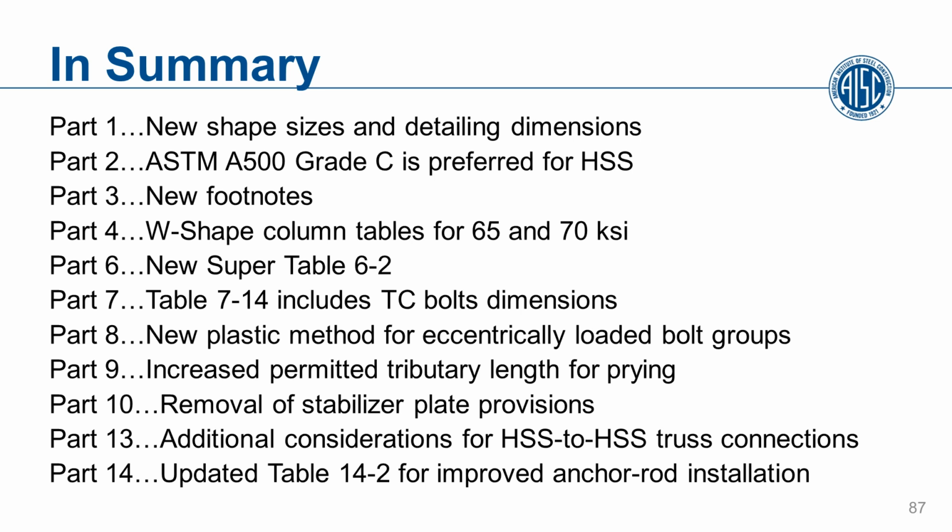Part 10 removes the stabilizer plate provisions for extended single plate connections. Part 13 has additional considerations for HSS to HSS truss connections. Part 14 has an updated Table 14-2 for approved anchor rod installation.